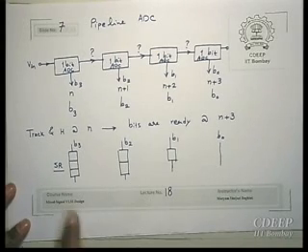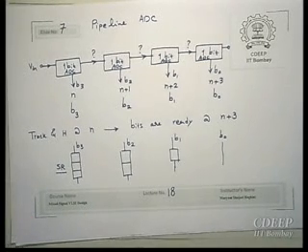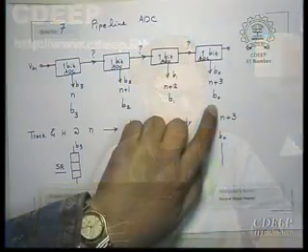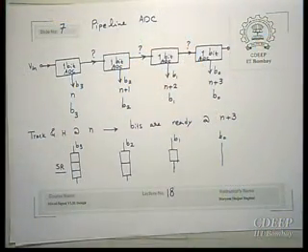The reason is that these bits are not available at the same time, so we need to take care of this delay. When your B0 is ready, your B3 has been ready 3 cycles before that. So where do you keep it? You need to keep it in a memory. Essentially you need a memory. This shift register is that memory.